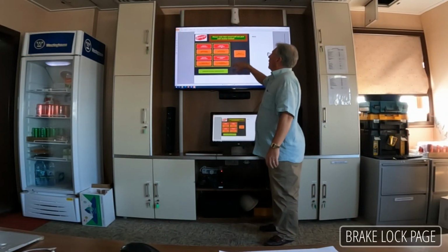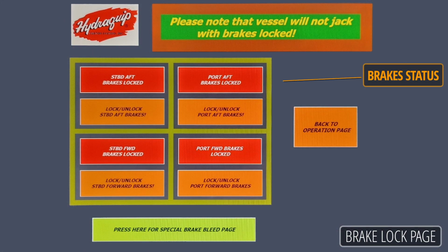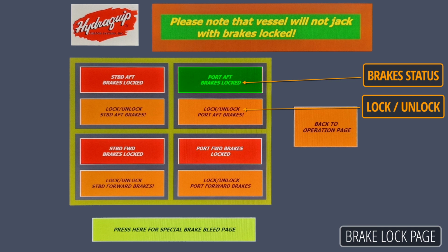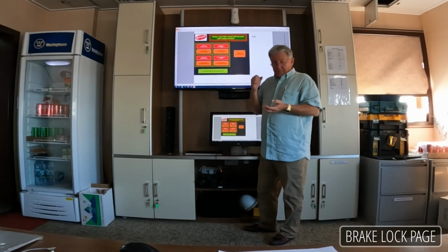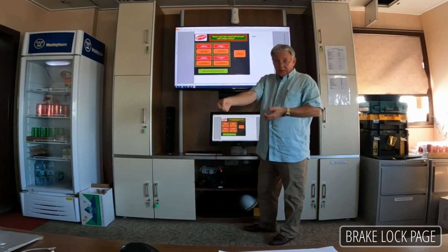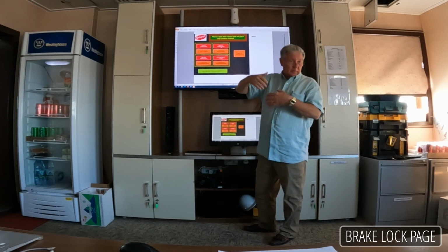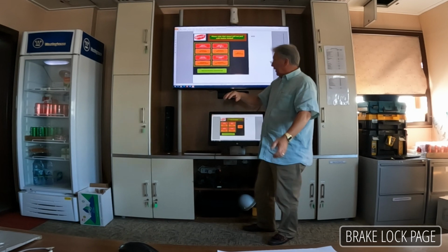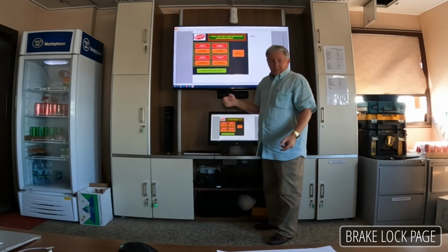This is the brake lock. On this page, when you press these buttons, these things turn green and the brakes can function normally. You press these, they turn red, and the brakes cannot get a signal. Therefore, sometimes we fire against the brakes so we can see what's happening with the pressure and joystick functionality, or you want to lock the brakes for safety.